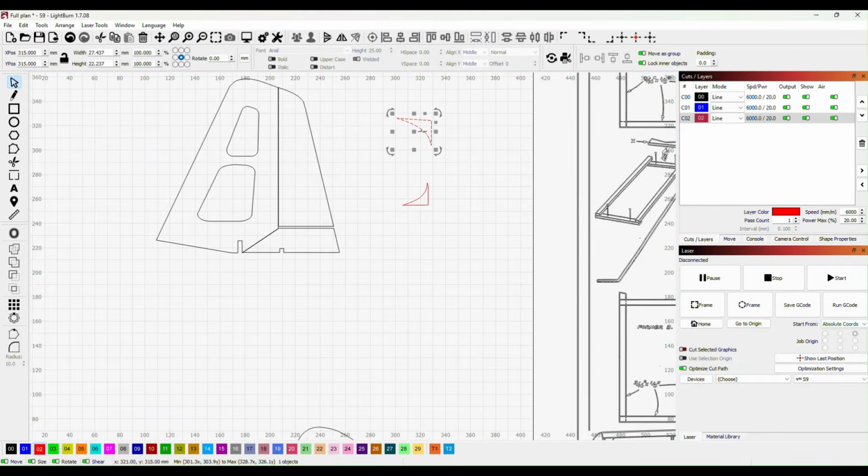So if I turn that into a cutting layer by clicking on it and then selecting this layer down here, 0, 0, and then we can label these up as F2 and F3. I'll just reduce the size of those letters. From up here it's 25mm, obviously far too big, so I'll make those 3mm because they are very small components. So we'll have F2 and F3.